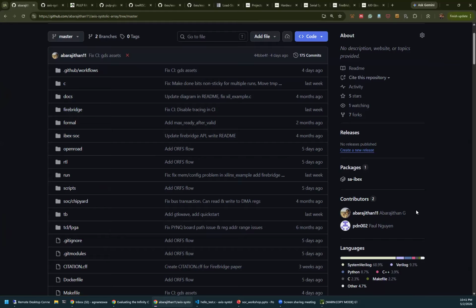The next step is, can you do it with Linux? You have Linux running on the ARM processor, talking back and forth with the accelerator. I think that is a little more valuable, because then you can send data through Ethernet or something, and Linux can handle all of that. You can boot Linux and use the accelerator as another GPU or something, which is very cool. If you're doing something on the FPGA, I recommend you do that.